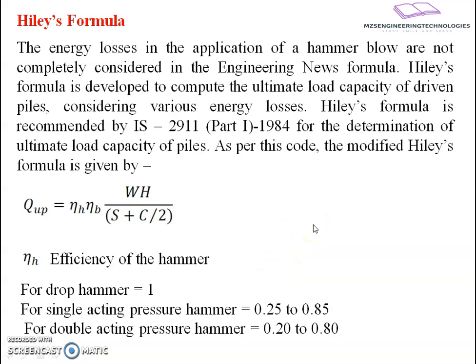Greetings. Let us continue with the part of discussion related to dynamic formulation. In the last lecture, we have seen the Engineering News Record formula, and we also started the discussion of Hiley's formula. Hiley's formula accounts for the energy losses in the application of the hammer, and it modifies the engineering formula. This recommendation was accepted in IS 2911, and the determination of the ultimate load pile capacity is given